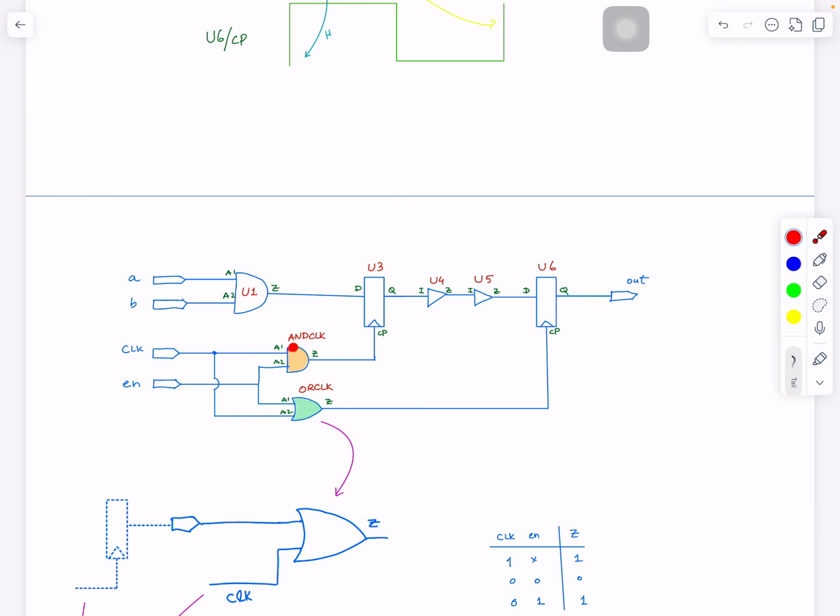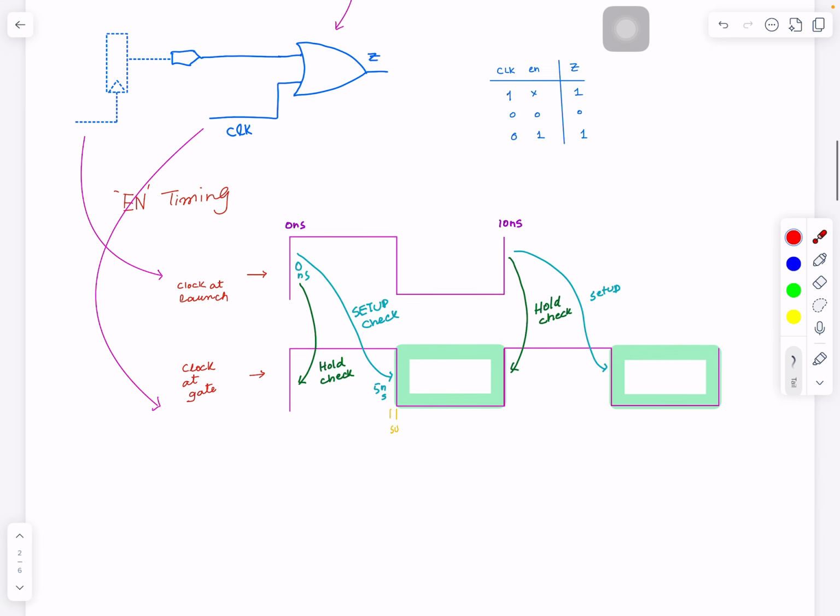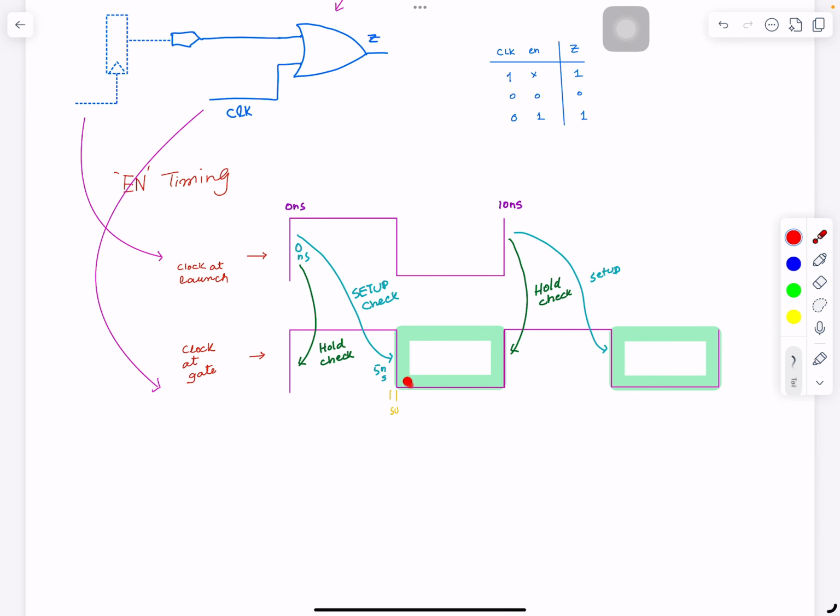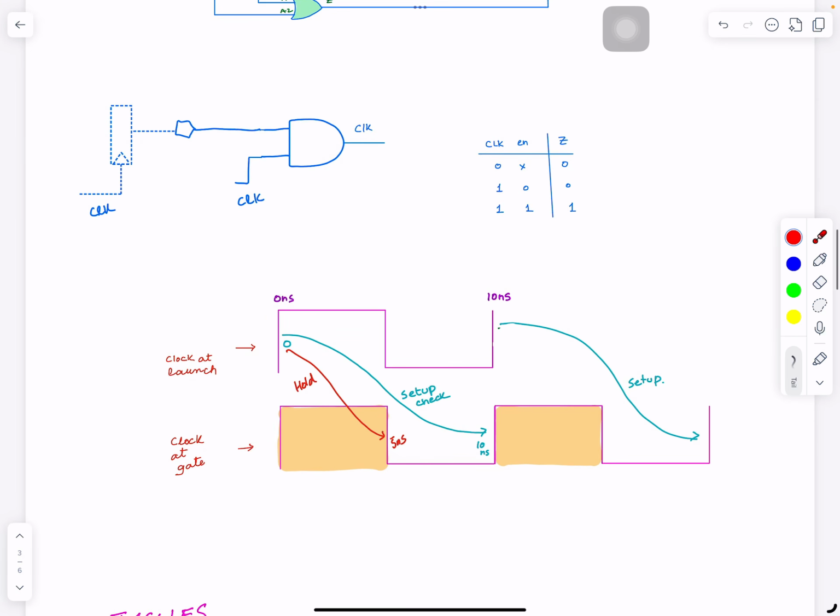It will sit somewhere in the middle or somewhere along the line. So delay is already pretty short here. This can be a problem depending on your clock or your circuit there. This is kind of independent of the clock. Well, if the clock period is bigger, you will have to put more delay cells. So the whole fixing depends on that too.